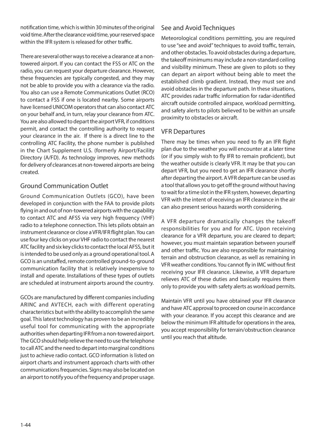Likewise, a VFR departure relieves ATC of these duties and basically requires them only to provide you with safety alerts as workload permits. Maintain VFR until you have obtained your IFR clearance and have ATC approval to proceed on course in accordance with your clearance. If you accept this clearance and are below the minimum IFR altitude for operations in the area, you accept responsibility for terrain/obstruction clearance until you reach that altitude.